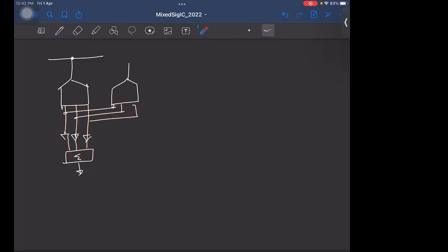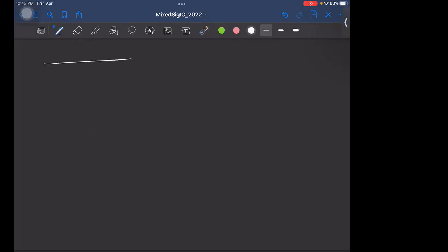So, okay. One last thing, say we have a 2-stage pipeline. And let us say the ADC here samples the input during phi 1. So in which phase did we say the residue amplifier must sample the input? No, remember why phi 2? Yeah, amplifying in phi 2, but you have to sample exactly in phi 1, right? Because this is the clock to the ADC, or let's say this is the clock phi 1.